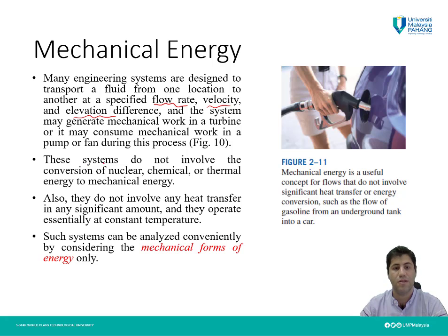And you should notice that this system does not involve any conversion of nuclear, chemical, thermal, or other energy to mechanical energy. The only form which is converted to mechanical work is due to its flow rate and velocity or elevation difference. And a system like this also does not involve any heat transfer or thermal energy transfer, or we can say it does not involve any significant amount. It may involve something like friction, but it is not significant compared to the mechanical energy or flow energy.